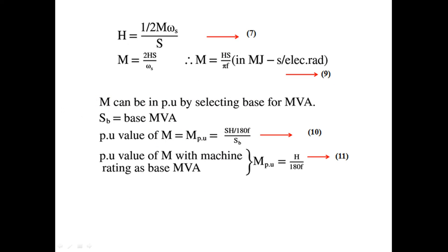Okay, so here after substituting the equation for E ke from the third equation in the fifth equation, I will be obtaining the inertia constant and also the kinetic inertia constant and moment of inertia. Okay, so here we know the omega formula. Generally omega formula is 2 pi f. So when I am substituting here, 2 will be cancelled and we get H by pi f. So this is represented in moment of inertia, electrical radian.